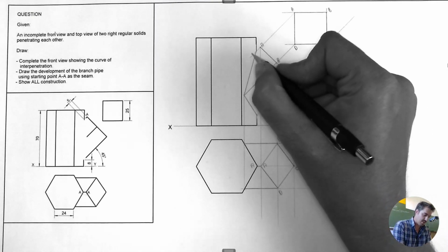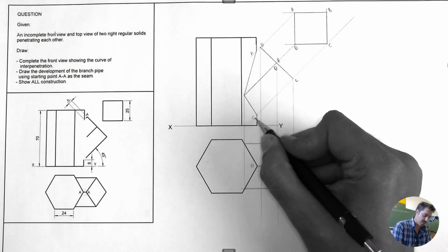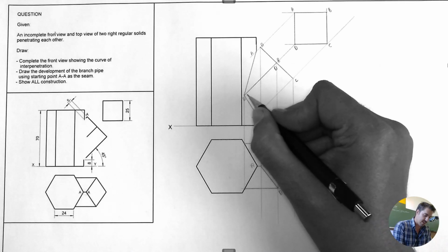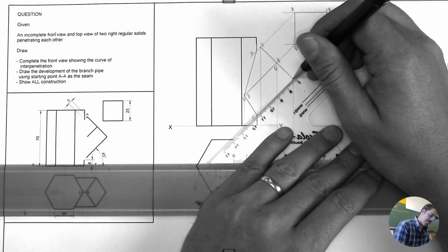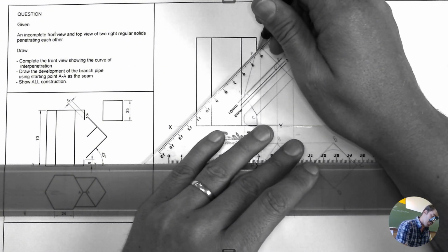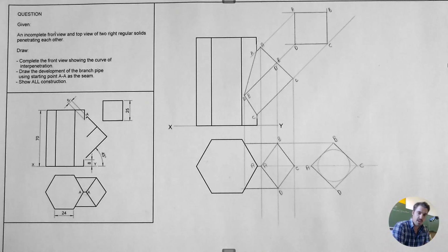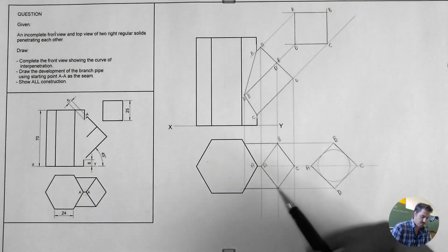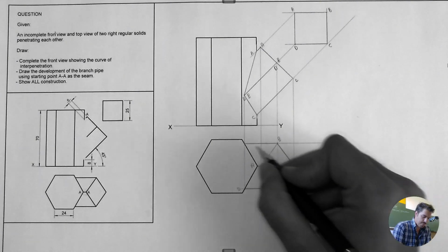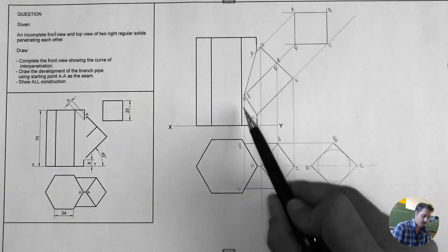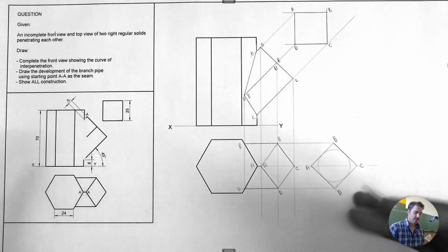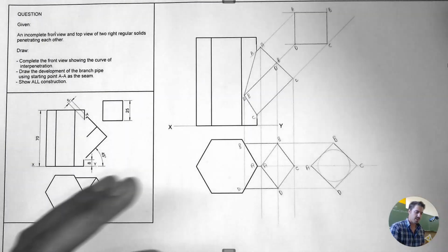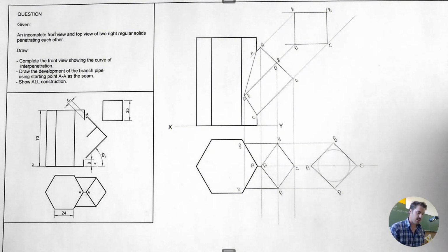So this is point A going to A, C going all the way to C, D going to D, which is visible. B is also here, but it's at the back. You can see it's exactly in line. So now you can go ahead and just connect the rest of your equality lines. So that is going to be the interpenetration done and dusted. That's what you have. Just make sure these letters D, B, they correspond with the letters that you have here. If it does, then you are fine. Alright, then you don't have to worry about looking at all the ways that this drawing turns, and from the front to the top, and vice versa.